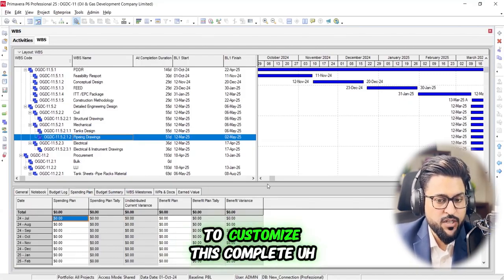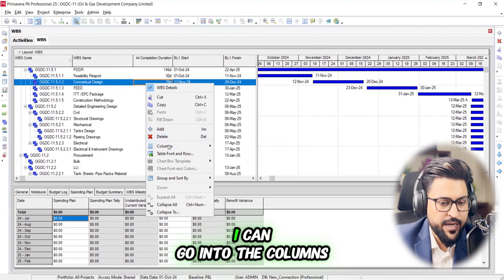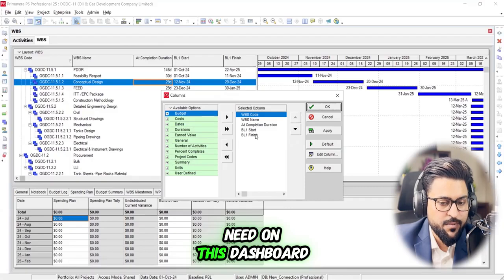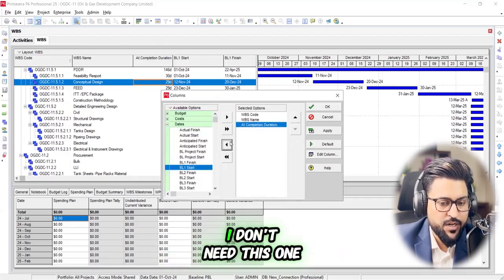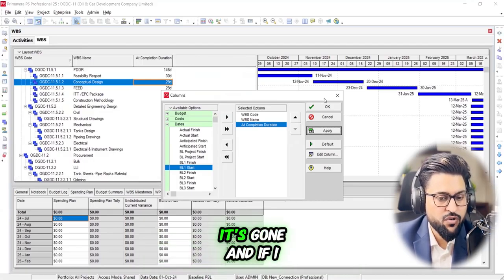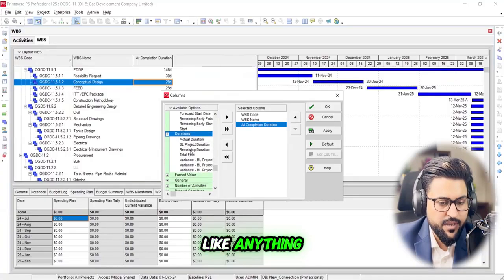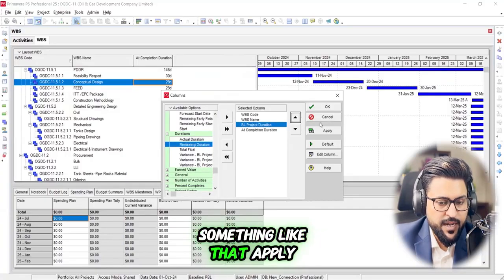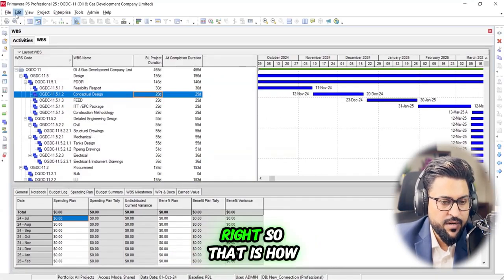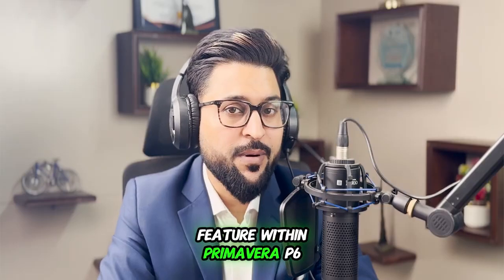At the same time, how to customize this complete dashboard. If I right click over here, I can go into Columns and customize what kind of information I need on this dashboard. I don't need this information, I don't need this one. I can just select these options, and move them to my left hand side, and you can see it's gone. And if I need anything out of this, like duration, baseline project duration, something like that, apply, okay, and you can find project. See, everything is there, right? So that is how you are going to set up your WBS. It is a very important feature within Primavera P6.